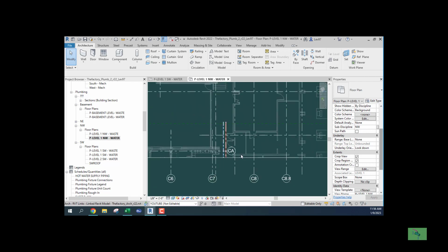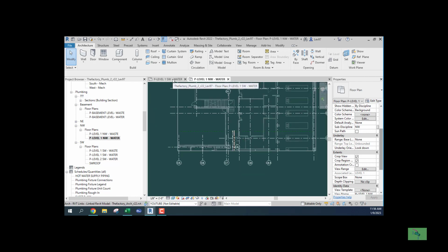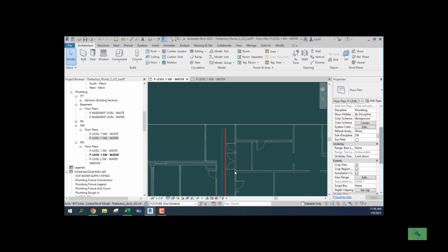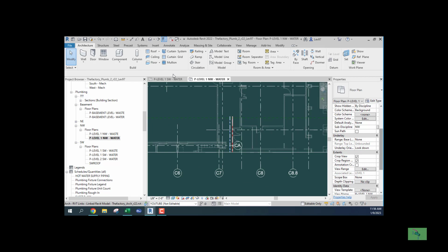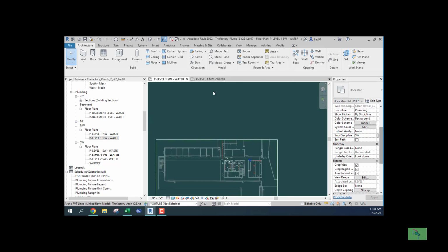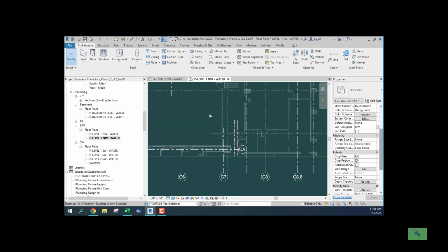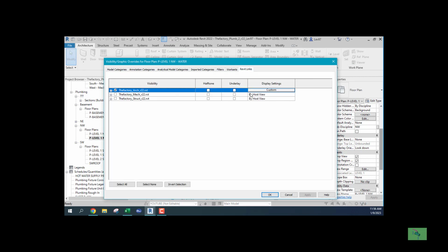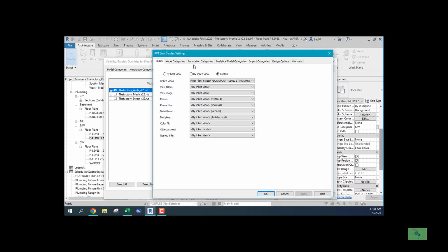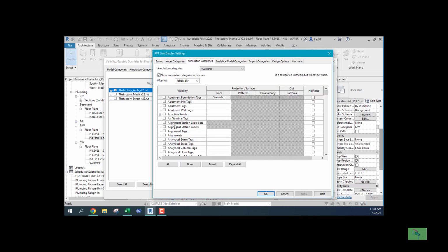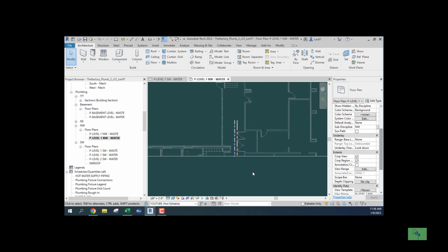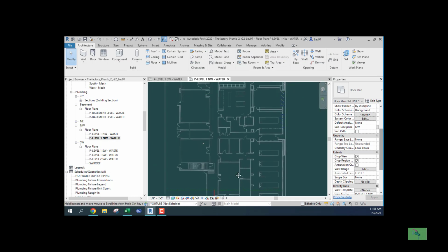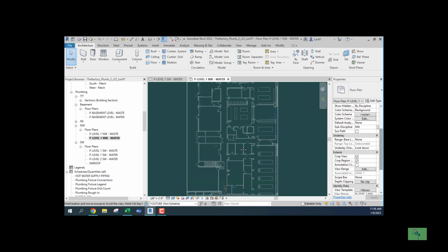Realistic view. So that's a continuation, okay? So we go from one drawing, which is, those are the three doors. And on the other side, those are the three doors. Okay, so I don't have the grids on. So I'm going to go in, type VV, and go back to custom, annotation, type G, and turn off the grids for now. Okay, and say okay to that. Okay, so now it's just more clear. So it looks okay.